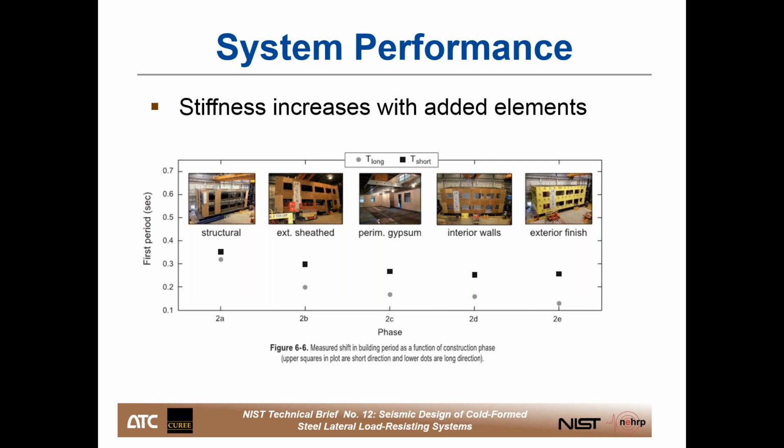One of the most interesting takeaways from the testing, though, was that the structure didn't perform at all how our simplistic engineering models predicted. So the shear walls were not significantly worked even at the highest accelerations. The non-structural elements added so much to both the strength and stiffness that it kind of threw our prediction models out the window a little bit.